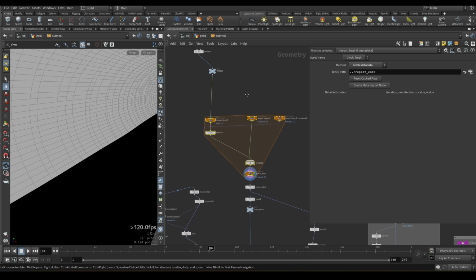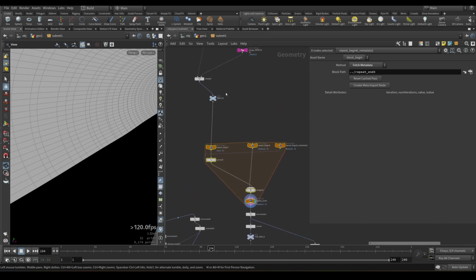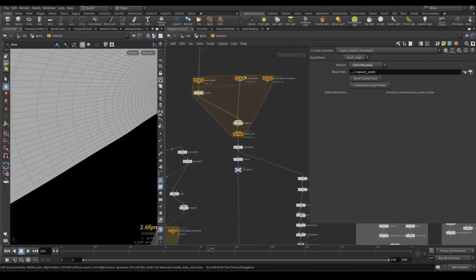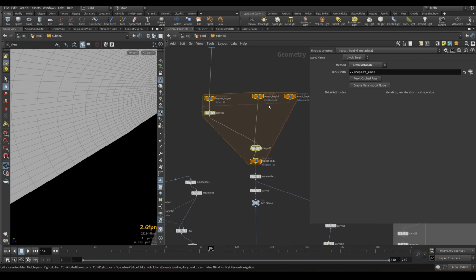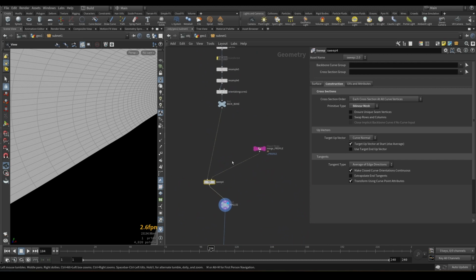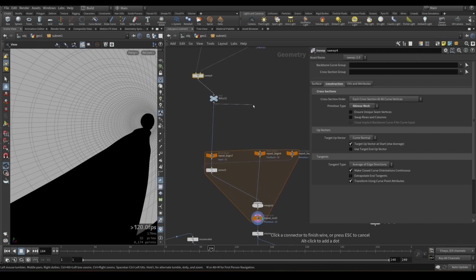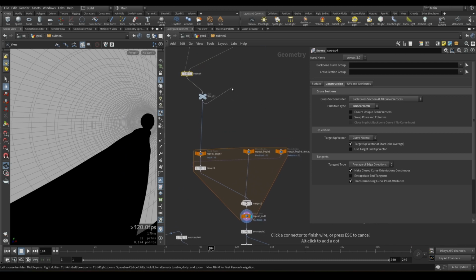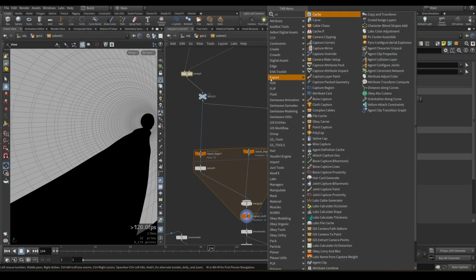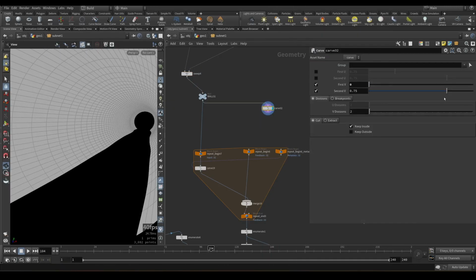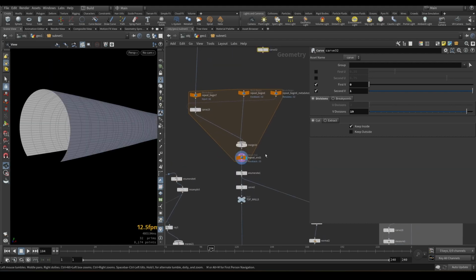Before we start, I wanted to clarify one pretty important thing. When we initially create our cuts, at the start of our setup, right after we generated the sweep, we used a repeat block to perform these cuts. But if we're happy with just uniform cuts, we can just use a carve node as usual, set first V and second V to 0 and 1 respectively. It could be first U and second U, depending on your particular case. And you can just increase V divisions. That way you have multiple primitives, which will be equal to this result.